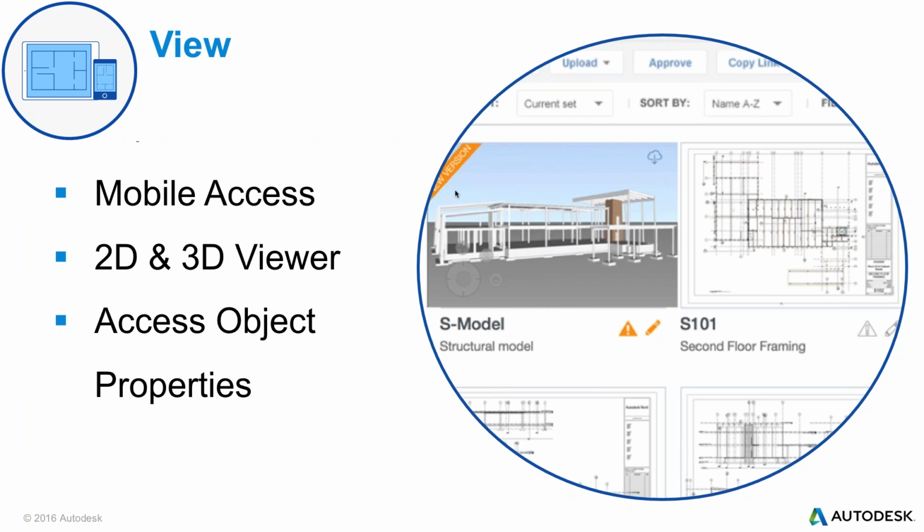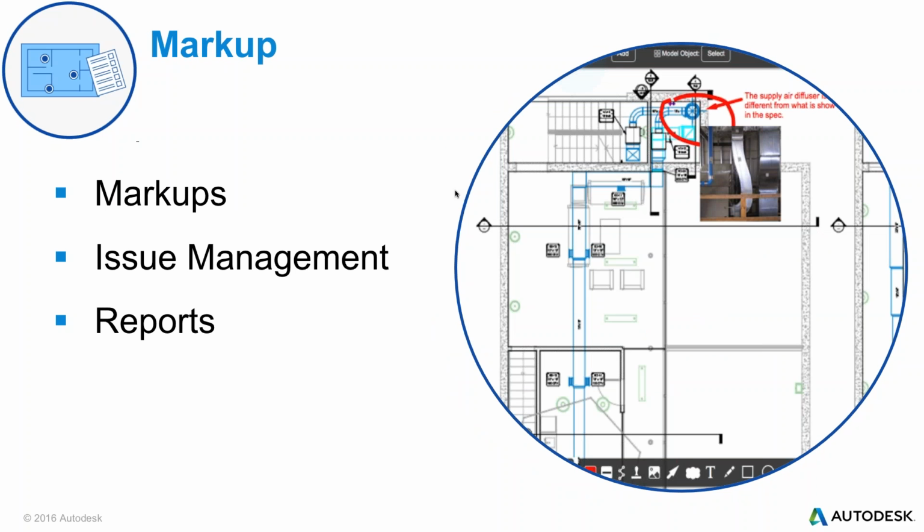Critically important to remember, when we save those Revit models, right, it does the hard work for us. It automatically extracts the sheet. For those of you that use Revit and have ever accidentally tried to print a PDF and you printed one sheet after another, and you've got 600 PDFs to view, this eliminates that. You don't have to make sure you check that Combine All button anymore. By just simply saving that Revit file inside of this folder repository, we gain access to all those sheets, all the properties, and all of those objects.